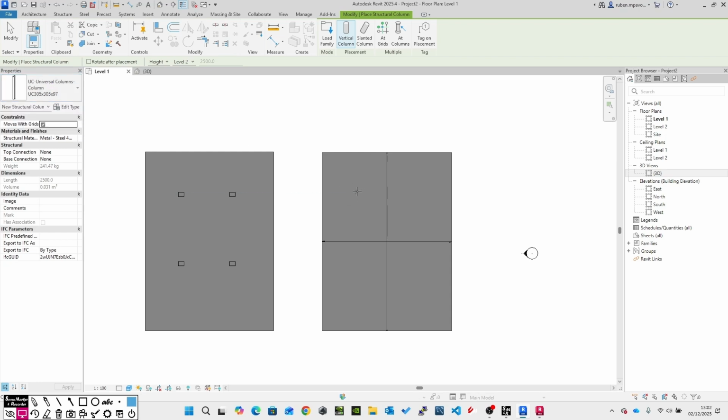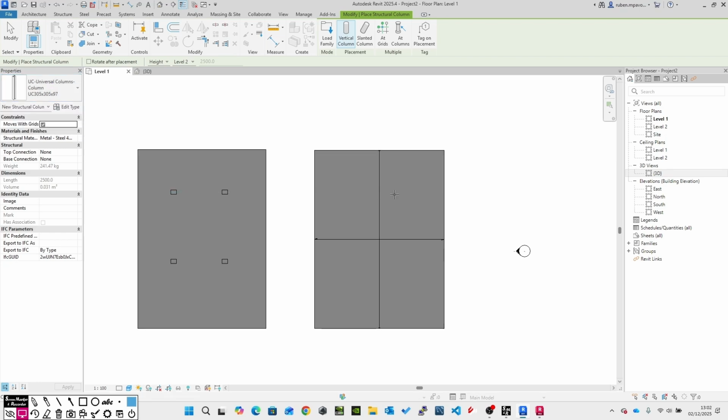I am going to place it into the structural part, that is the right side elements. So be careful, because the structural columns always grow from the level down to the inferior level. So it's important to see these properties and say, okay, I'm going to grow the column in height from the level 1 that I am on to the level 2.